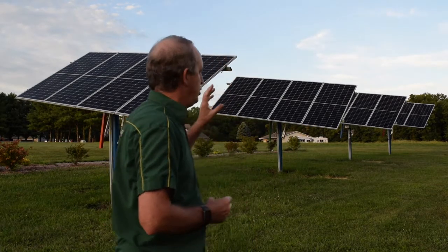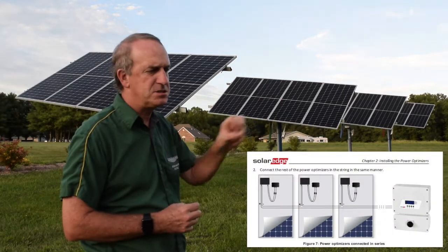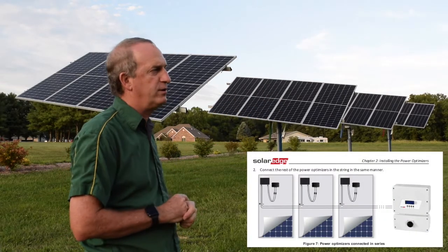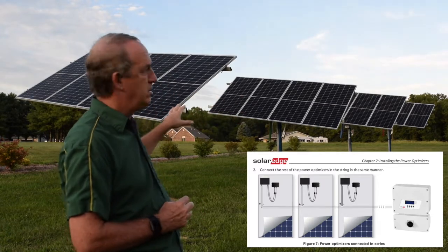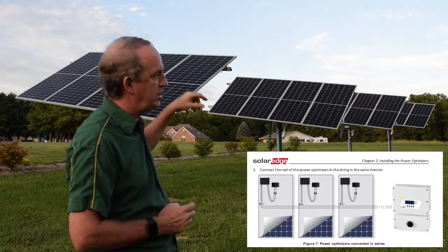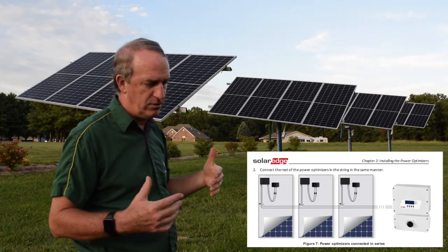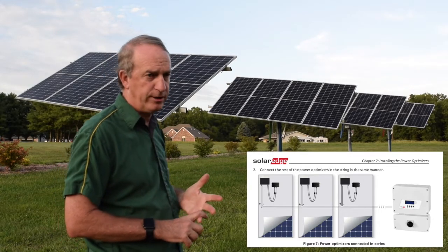All right, so you've got your solar panels, they're adding up in series. The optimizer in my case is telling them exactly what voltage and current to deliver. And so I've got 2 strings here. There are 8 panels on each string, 2 poles on each string, and that'll generate 400 volts and 15 amps of DC current.